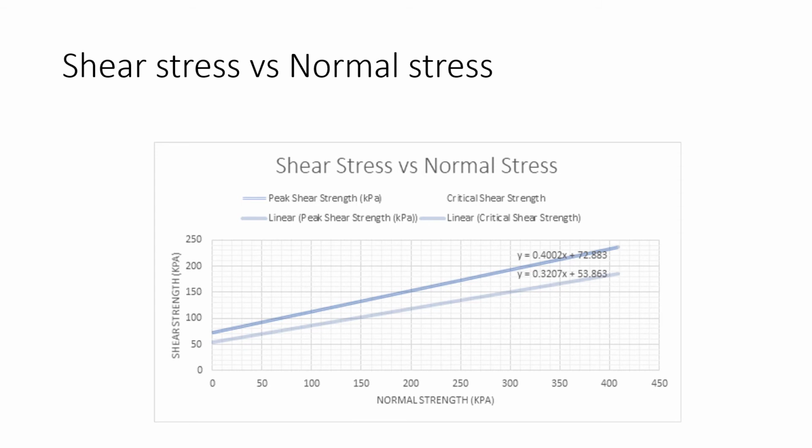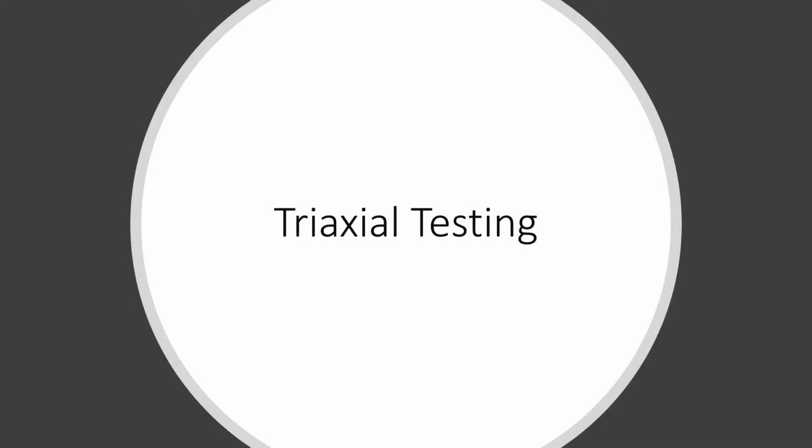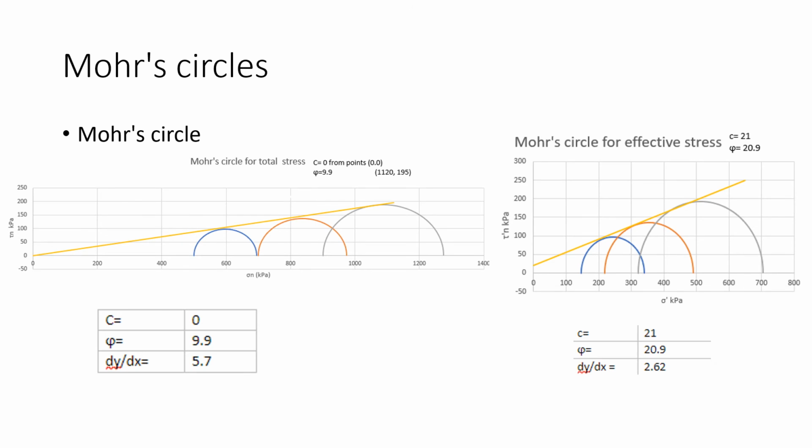disposal centre. Triaxial testing is used in order to model the long-term behaviour of soil, in particular of soil in a slope. For this test, we were testing it in CU conditions. We were able to use the data provided to manipulate the figures in Excel into plotting our Mohr circles and finding the angles at the tangent.